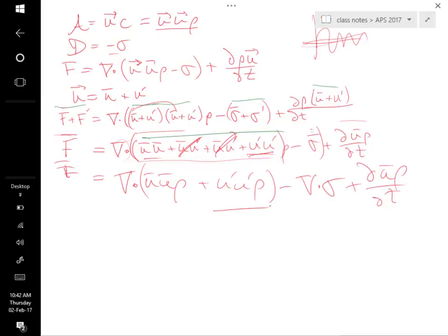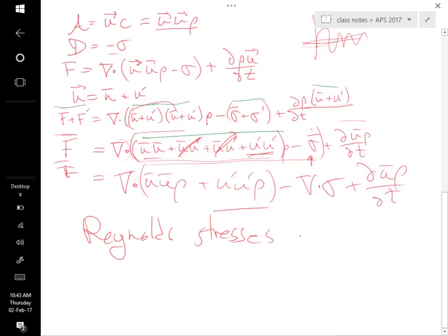velocities. And it has the same units as stress. You know, in fact, we wrote it up here, grouped together with the stresses. So it behaves like a stress, and in fact, it's called the Reynolds stress. Reynolds stresses. And it's the u_i u_j times density, perturbed. Okay? So what we need to do is deal with that.